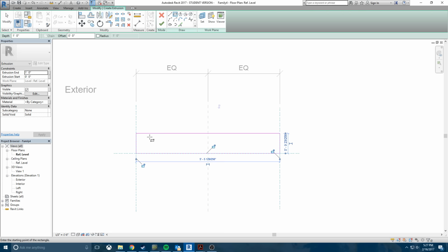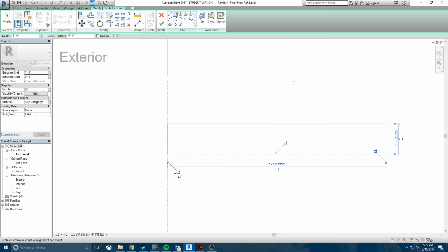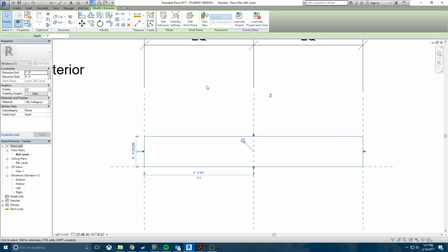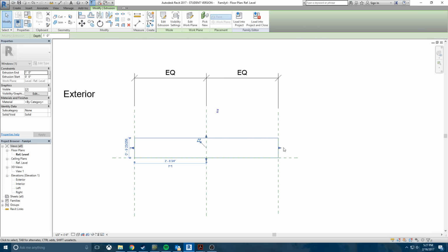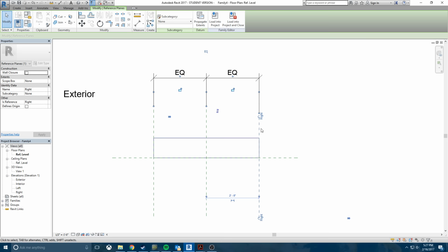When you create this, a lock symbol will show, and if you click on it, that will lock the edge to the side. So lock these edges to the sides and hit the green check arrow. What happens is that when we move these planes, our object moves along with it.